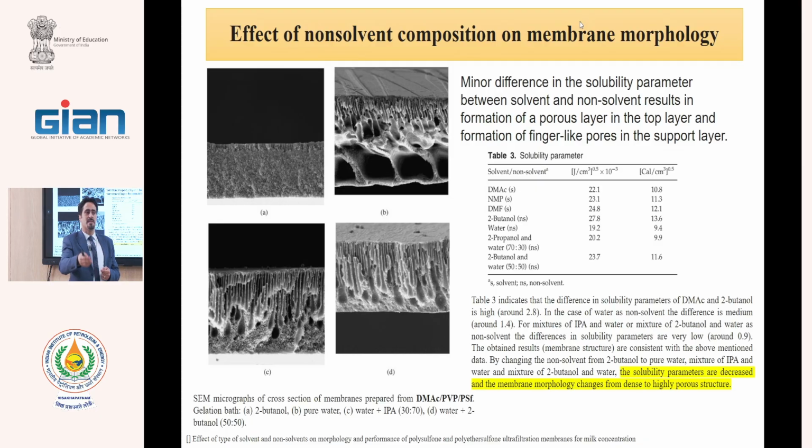After 10 minutes in the continuous production of membranes, our non-solvent is not pure, because the solvent comes into the water and we have 1%, 2%, 3% of solvent. Therefore, in the industrial state, we do not have pure water as a non-solvent, and we have 2, 3, 4% of solvent. Therefore, we must investigate the effect of the solvent as an additive in the non-solvent.